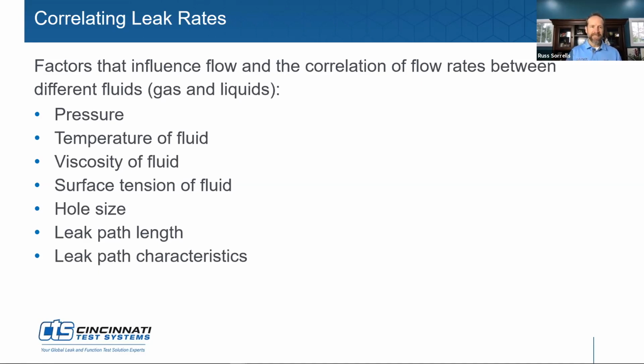Just to be more specific on exactly what we're trying to correlate, we had a customer do that many years ago, and one of the challenges that you'll find, especially in the automotive industry, is that your parts heat up, and when they heat up, of course, they expand, and that can create some different flow rates due to temperature and expansion as opposed to a standard temperature that you're going to test at, room temperature, which is ideal for pressure decay and mass flow.